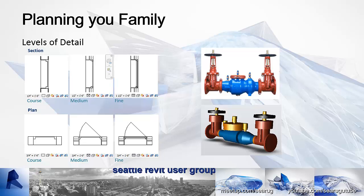So on top of how it is going to look in 2D versus 3D versus elevation, the Autodesk Seek guidelines have really started to develop best practices for representing your content. Right here I've got a valve situation, and then I've also got a window placed inside of here. In Revit we have detail levels. We can start to take a look at different graphic representations, not only in plan, in 3D, elevations, sections, and so on and so forth. According to the Autodesk Seek guidelines, we have to develop content with a minimum of 2 graphic representations for each view.